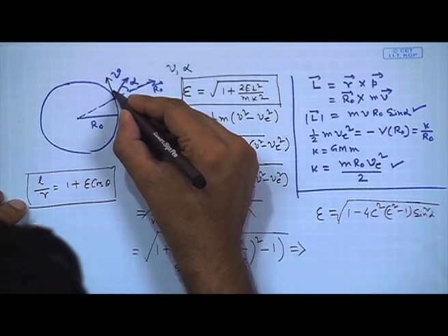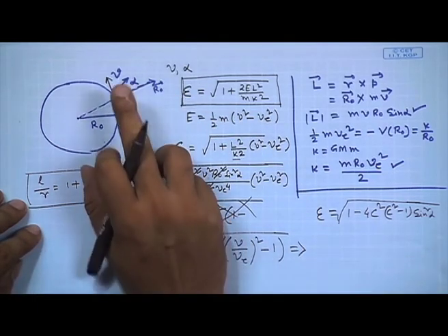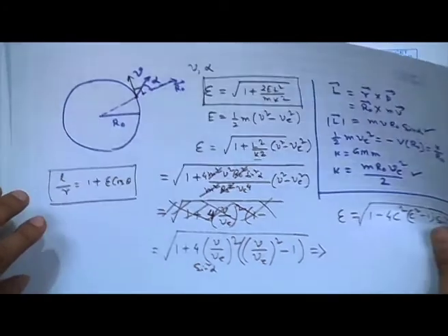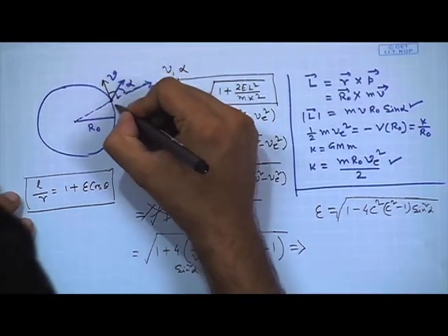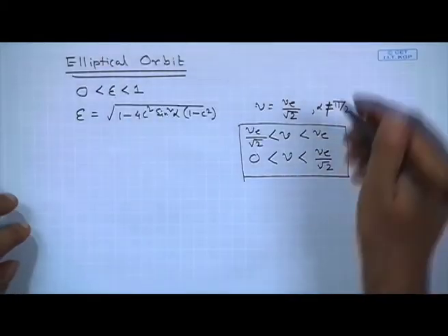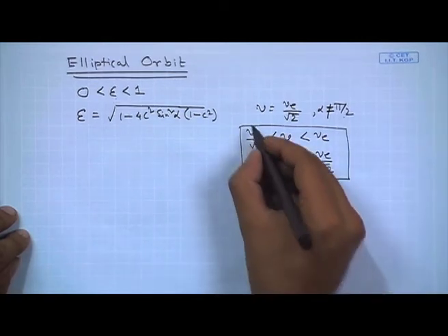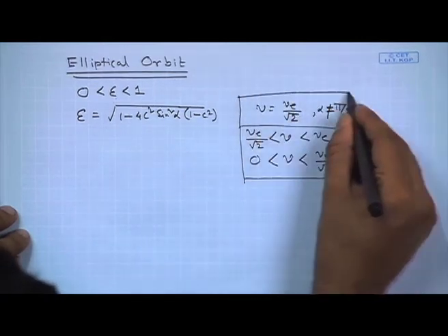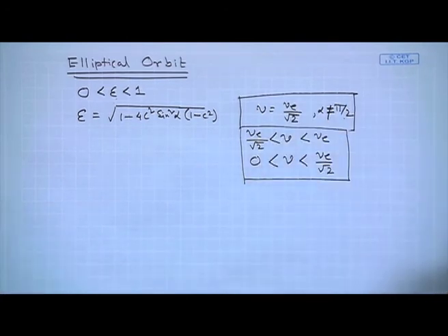So it has to be launched horizontally, right. So this is the condition for a circular orbit. Now if the velocity condition for a circular orbit is met, but our angle condition is not met for any other alpha, we can also have an elliptical orbit. So essentially these are the three domains in which we can have an elliptical orbit, right.